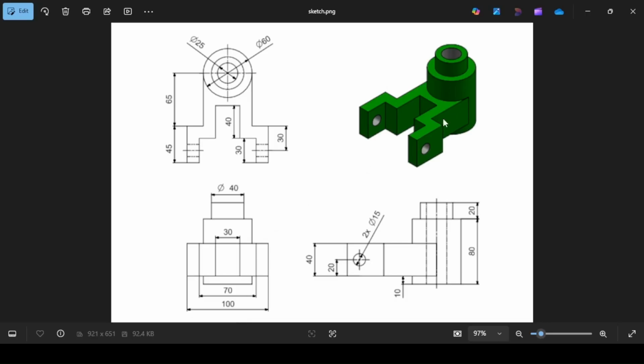Next, you are going to draw this first block that is attached to the cylinder. We use the front view here to get the rectangle for the block, and then we extrude. So first draw a rectangle of dimension 60 millimeters, which is the diameter of this outer circle, by 40 millimeters, and we extrude by 65 millimeters.